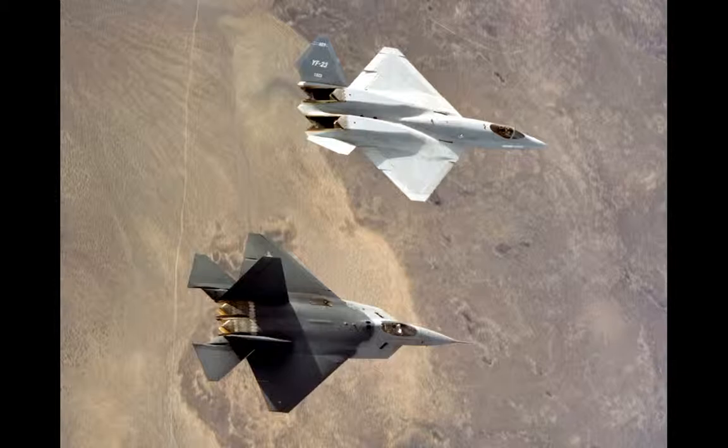Then you have performance requirements, like, well, we want you to have a max speed of Mach 1.5. Then you have basic physics in terms of laying things out, where the wing's going to go, where the tail's going to go, and then things are really driven by the systems engineering process of putting everything together, so the cockpit really has to end up being up front. There's nothing that really dictates that, other than trying to lay everything out and making sure you meet those visibility requirements for the pilot. But there are also a lot of subtle differences between these two designs.